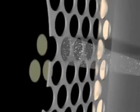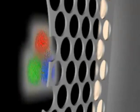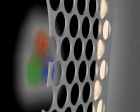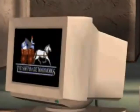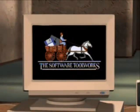A sheet of metal with holes inside it helps to keep the electron beams aligned exactly with the phosphors. This is called a shadow mask. The beams sweep across the entire screen 60 times per second, so quickly that you are unaware of the firing process. Instead, your screen appears as a steady continuous image.